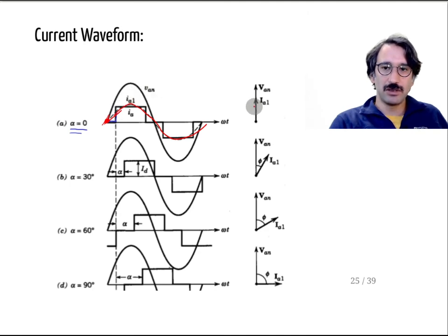So in other words, in this one, displacement power factor is 1, they are in phase. And if I just move my firing angle, and you just take the fundamental component of that, you will see there is a phase difference of alpha. So we had the same relation with the single phase thyristor rectifiers.